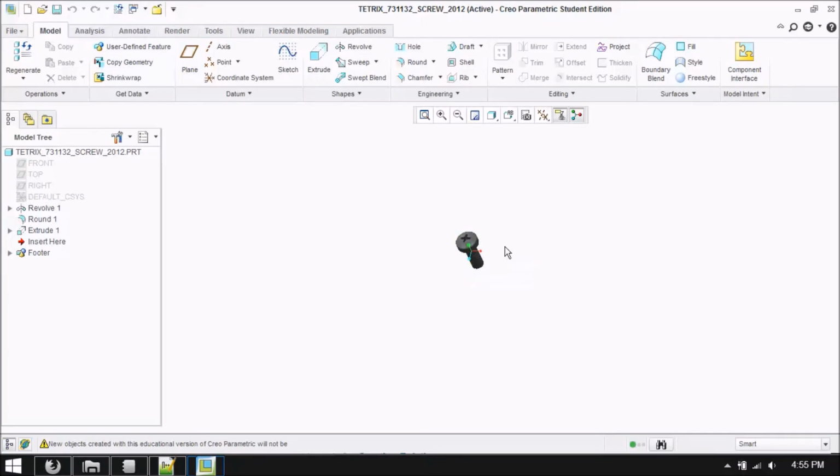One of the next things is swiveling. If I want to see a different side of this screw, because the opposite side is so different from this side, how I do that is I push down on the mouse wheel, the scroll button of the mouse, and I just move the mouse, and that will pivot the screw at the center axis point. The center axis point is where you see the two red lines and the dot right now. So it's going to pivot and swivel all around that so I can see all the different sides of the screw.